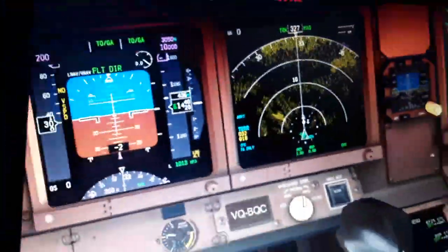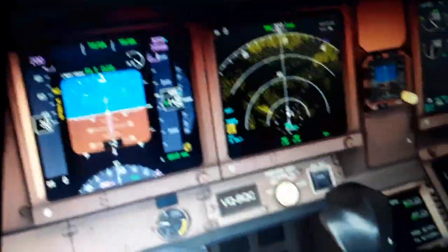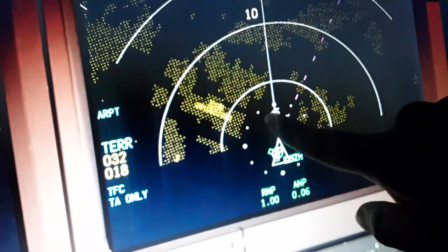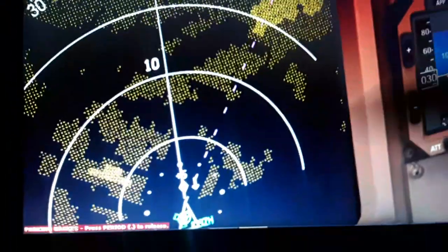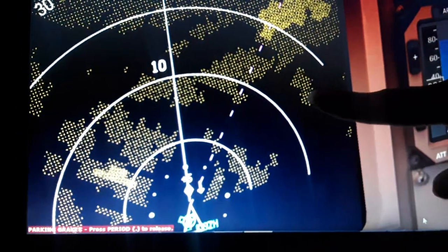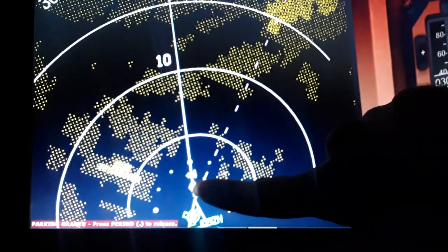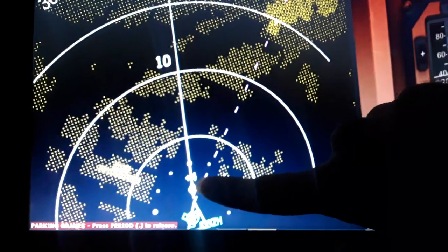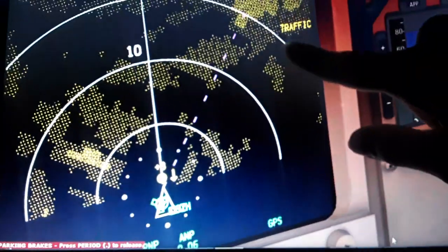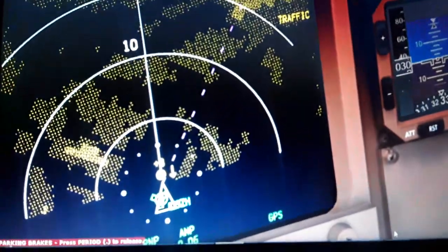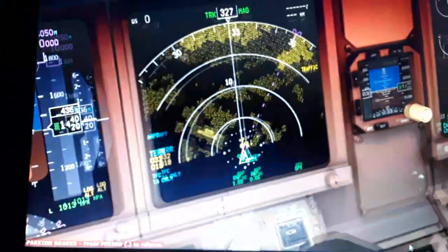We're gonna see the runway also. So we have plus 2.5 nautical miles, plus 500 feet. We're gonna have the traffic now, the warning displayed here using this aircraft. Plus 400, you will see it displayed in yellow now, plus 300. And we have the traffic coming in.